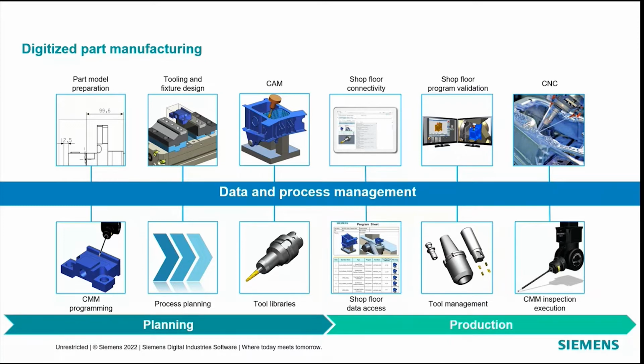All of those things are used inside of NX. We call it our in-process workpiece. So as the part gets machined, we always know exactly what the remaining stock is. So if you take that and move it to the next fixture or flip it over, whatever the case may be, or transfer to subspindles, you know exactly the amount of material that's remaining and the amount of material where you would be clamping, if you're leaving some there to be cleaned up in tertiary operations. And then obviously into the toolpath capabilities, and then all the way to shop floor connectivity. We can do the validation out on the shop floor, and then obviously run that. And that all has related applications, right? Which would be that whole data on the bottom there. If you needed CMM programming, XCMM is there.